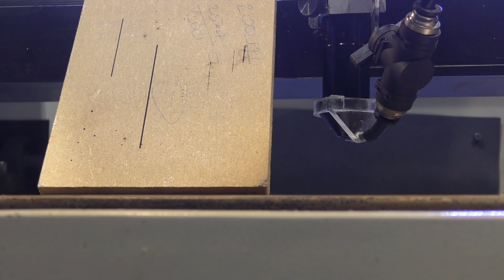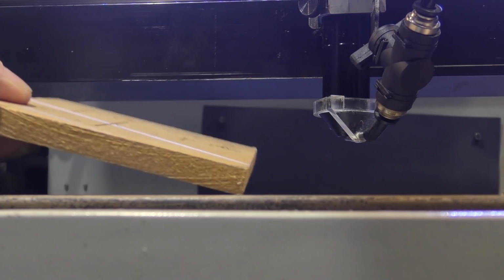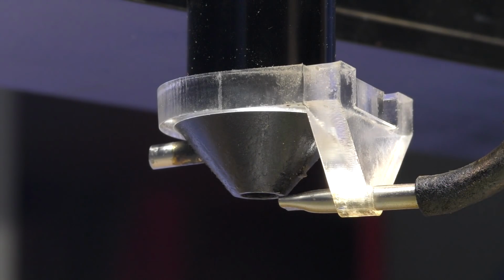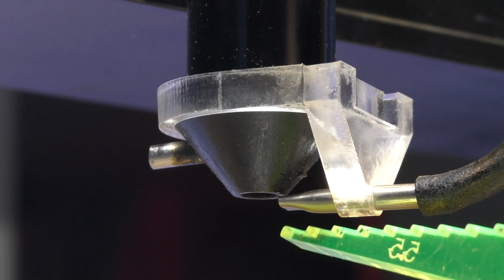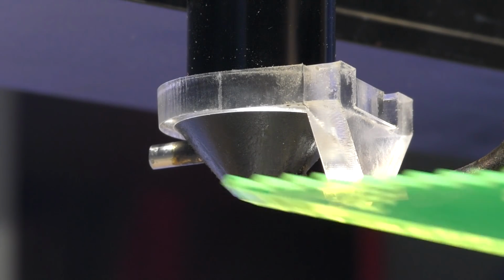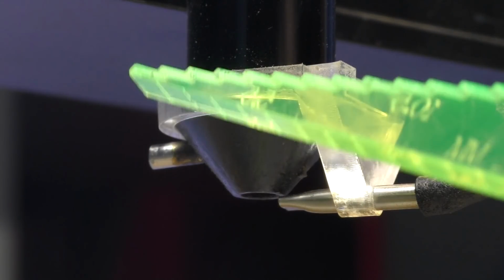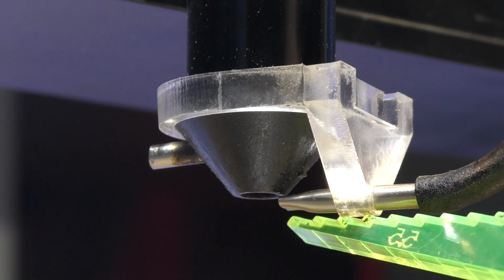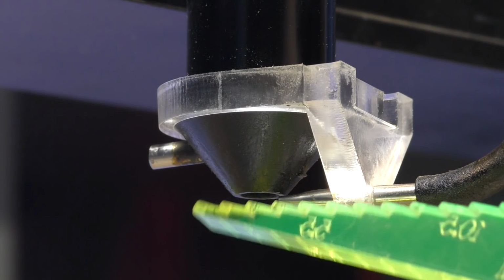Based on what I've just seen in my video, I've modified the air assist. I've still got my short engraving nozzle on here with a big hole in it, but look what I'm doing this time. I've got my air assist disconnected from here. I'm not blowing it through the nozzle. I've got it connected to a little fishtail, and I'm blowing it across the nozzle.